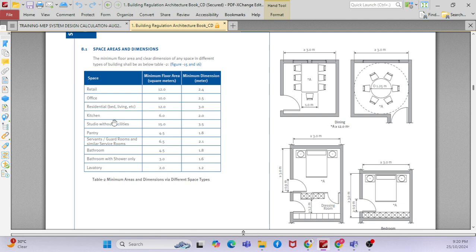Say for example, you have a balcony, you require a floor drain, right? You may provide some water taps, a hose bib for the balcony. If you understand the architectural space, if you go to the basement to clean the car parking, you have to provide hose bibs to clean the parking area, right? If you go to the plant room, you will provide a hose bib. Why is the hose bib required? To clean the plant rooms. Or if you need any water supply, say there is a leakage in the chilled water system, you can take the water from there, provide it immediately, or you can clean that.